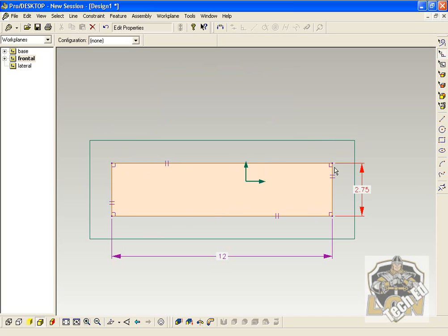Well, we need to put a slight slope on. And this is where it gets a little tricky. So I'm going to click the tool down here. It's the bottom one, and it's the Trim tool. I'm going to trim out the 2 lines that we did not dimension.